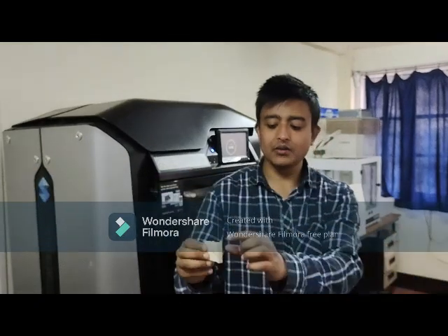So we just need to dip it there and increase the temperature. Talking of the temperature, for different materials we have different temperatures, like 70, 80, 60. Depending on which material we are using, we set the temperature there. So the heaters are heating the water along with those chemical agents, and it is removing the support material. After this is removed, we will get the proper part. Fine. So in the next class I will show you how we print the thing.